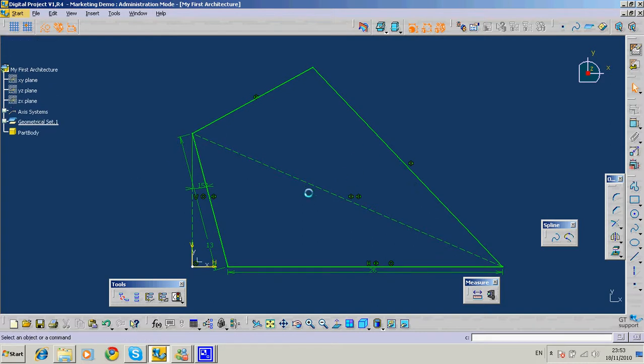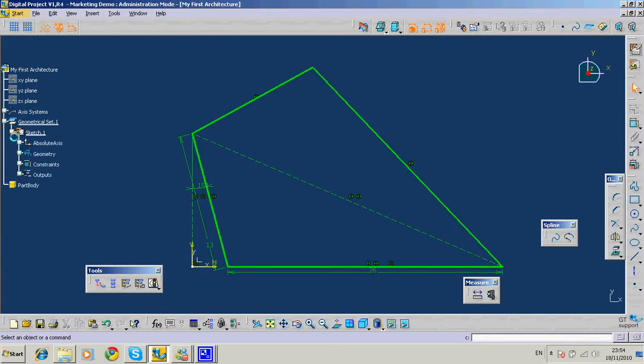And before we move away from the sketch, we also need to output features of these four lines. So we just hold Ctrl down, pick the four lines, and use this output feature. If you check your sketch output, you have these four lines. We also need to output those 4 points as well. Just pick those 4 points using the same. You got the 4 points.